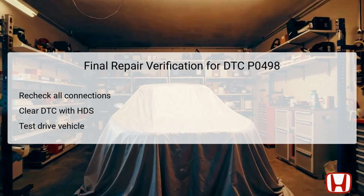After all repairs and troubleshooting have been completed for DTC P0498, it is crucial to perform a final verification of the repair. Start by carefully rechecking all connections related to the EVAP canister vent shut valve and the wiring involved in the circuit. Utilize the HDS to clear any remaining DTCs to enable an accurate read of the vehicle's current state.